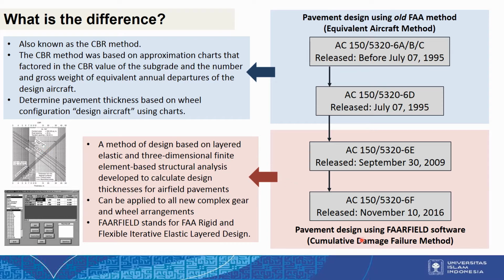And FAARFIELD software, or the cumulative damage failure method, is a method of design based on layered elastic and three-dimensional finite element structural analysis, developed to calculate design thickness for airfield pavement. So for the FAARFIELD software, the method is also upgraded. They use layered elastic and three-dimensional finite elements. As you know, finite elements are a little bit complex to calculate manually, so we need software to calculate the finite elements.